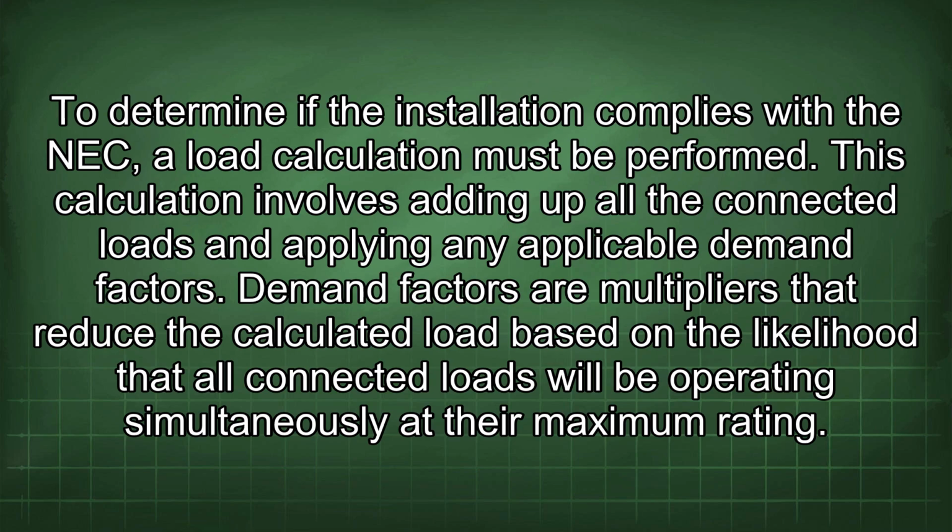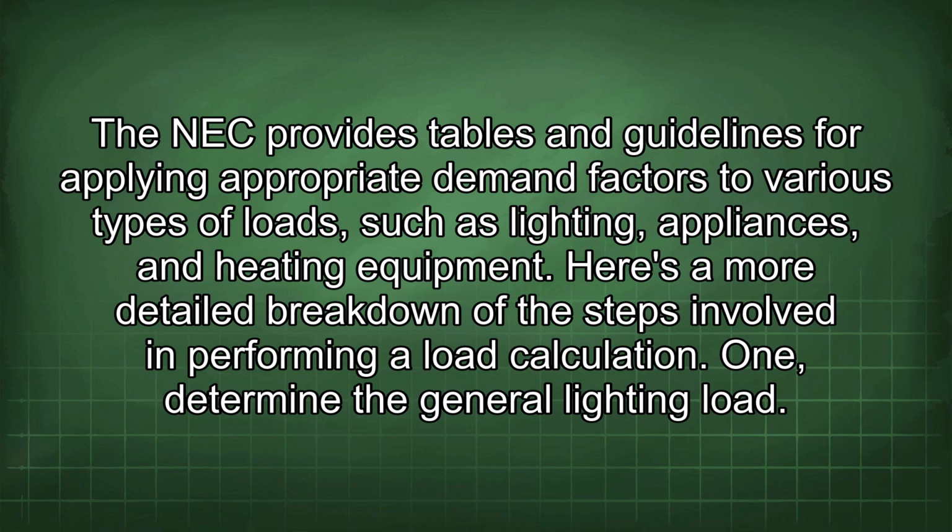This calculation involves adding up all the connected loads and applying any applicable demand factors. Demand factors are multipliers that reduce the calculated load based on the likelihood that all connected loads will be operating simultaneously at the maximum rating. The NEC provides tables and guidelines for applying appropriate demand factors to various types of loads such as lighting, appliances, and heating equipment. Here is a more detailed breakdown of the steps involved in performing a load calculation.